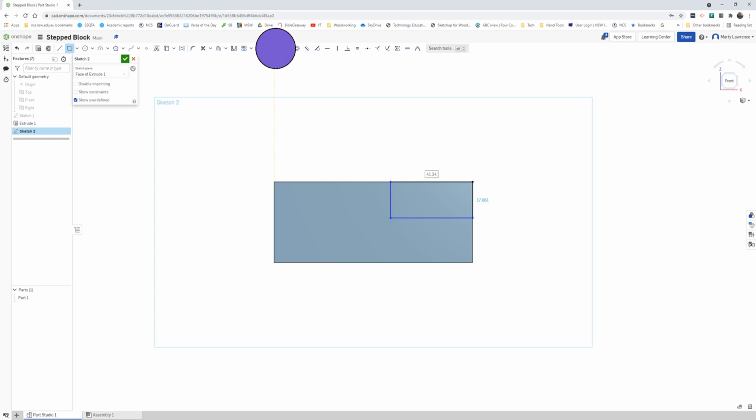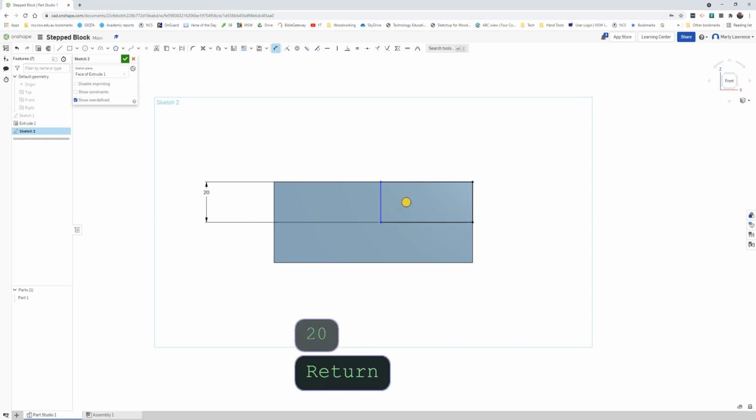We're going to use our dimension tool, short edge. We're going to set that to half of 40, which of course is 20. And we're going to set this dimension on the long edge of that new rectangle to 50. So we could use this or this, it doesn't really matter. If you're ever struggling with your maths, we can let the program do the maths for us. So we know we want 100 divided by 2, so we can type 100 divided by 2. Press enter, and it does the maths for us.